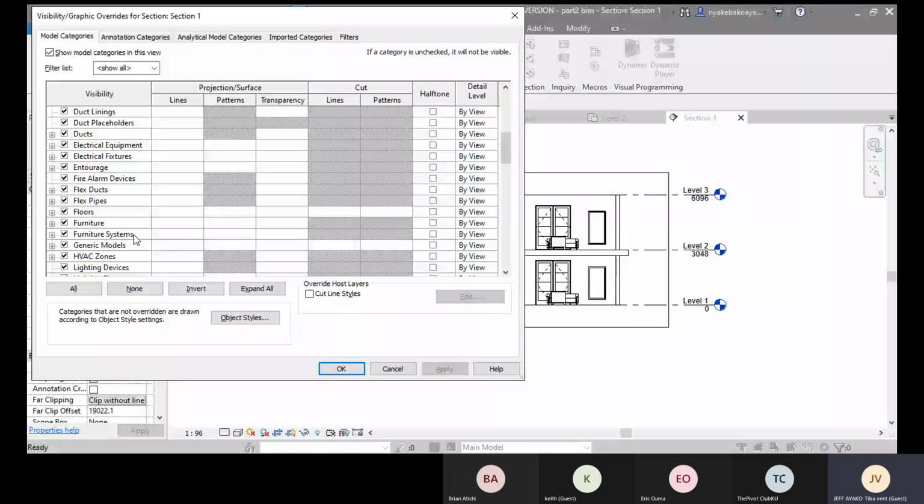So once you are done with that, then you need to create what is known as an analytical model. That is the model for your energy analysis. So once you click that, it will tell you are about to create an energy analytical model that will take considerable time, during which Revit will not be accessible. So once you start creating your model, you cannot do anything.